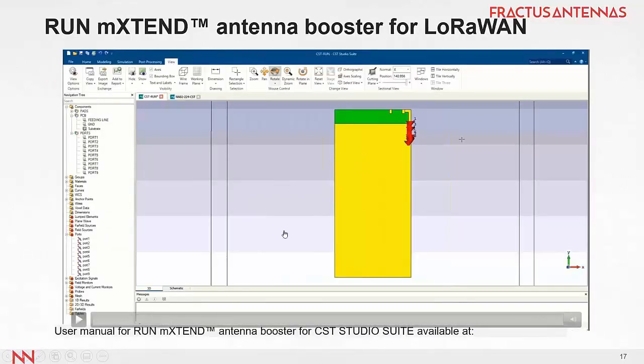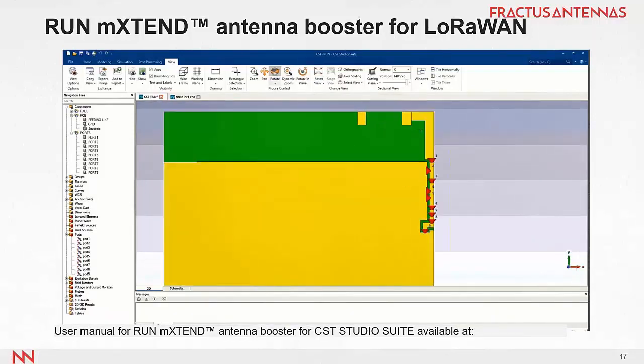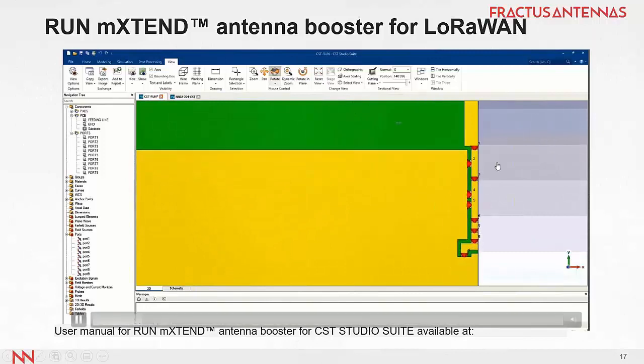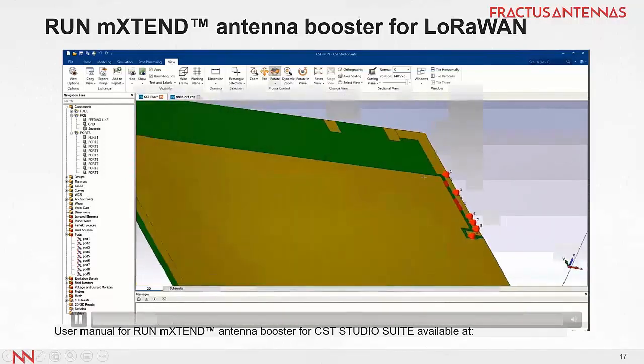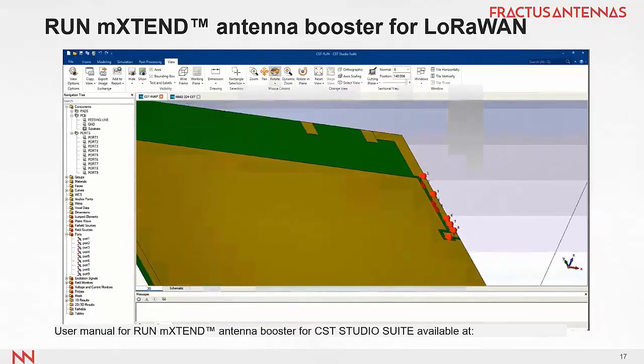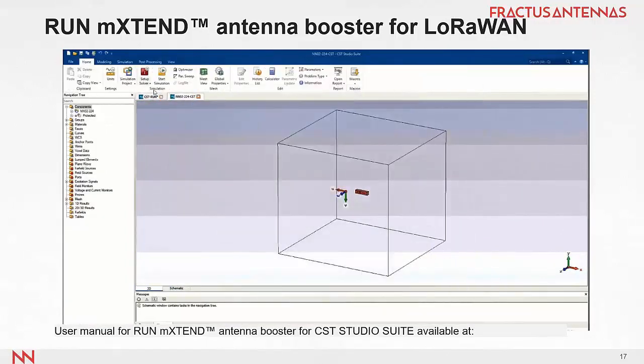Imagine you have your PCB. This is a particularly easy example, non-populated. At the end, we are going to see a populated PCB, but just to start with a single example. This is your PCB. In green color will be the ground plane. In green will be the dielectric of your PCB. Typically it's FR4 for most wireless devices. In here you can see the pad layout for your matching network. It can be reduced if you have fewer components. In this case, we put more space to allocate more components.